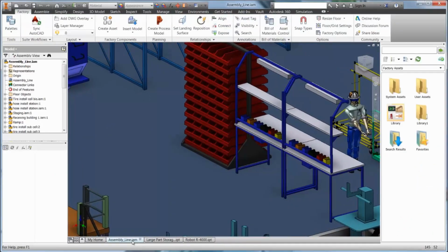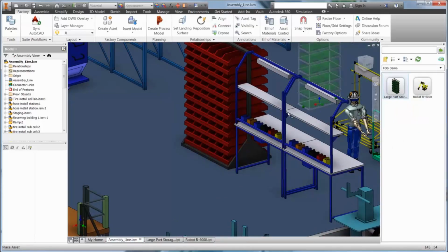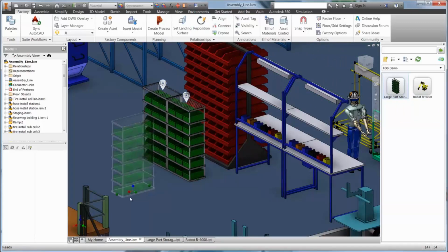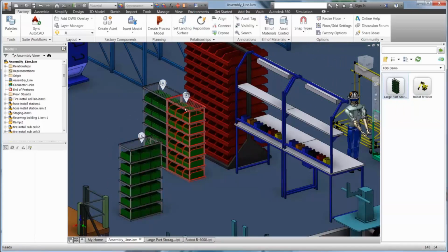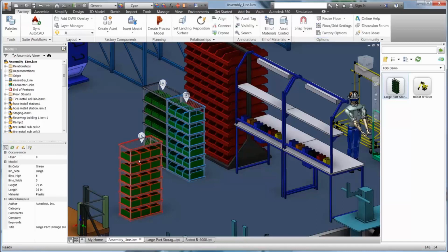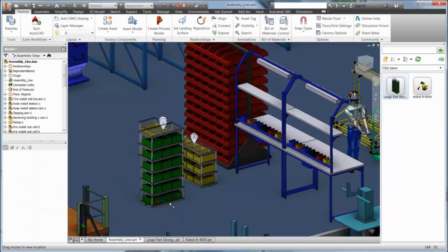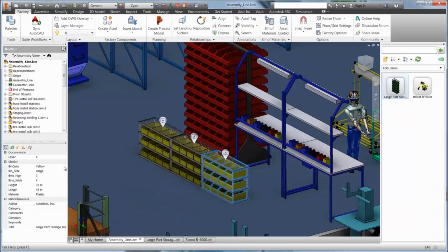When we use assets inside of our design environment for the factory layout, we use them through the library, and the library is defined in a reasonably logical order because you define it, and we just drag and drop those components in place. You'll notice that certain items have tags above them. In this case, the storage rack does. We can change these, and any interconnected components will change as a result. You'll see that the other one that wasn't connected doesn't change, but the moment that we drag it in place, it does change to reflect the properties of the others.